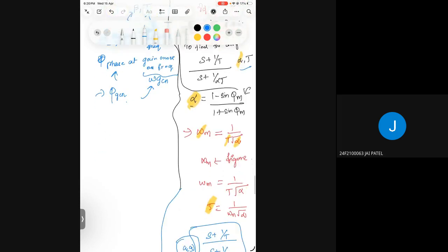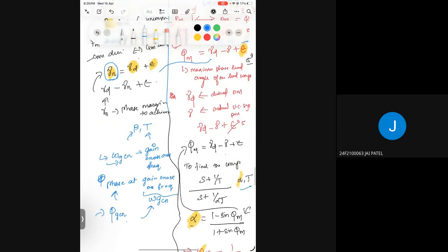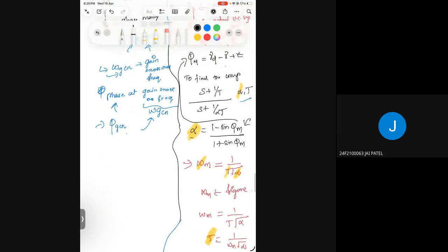So now this needs to be achieved, right? That is your gamma D plus epsilon, where gamma D is being asked in your desired phase margin. Epsilon is some compensation we add, just these two terms. If you want to compare it against your lag compensator, these two terms, the yellowish terms. Just what is desired, that's it. That is your gamma N.